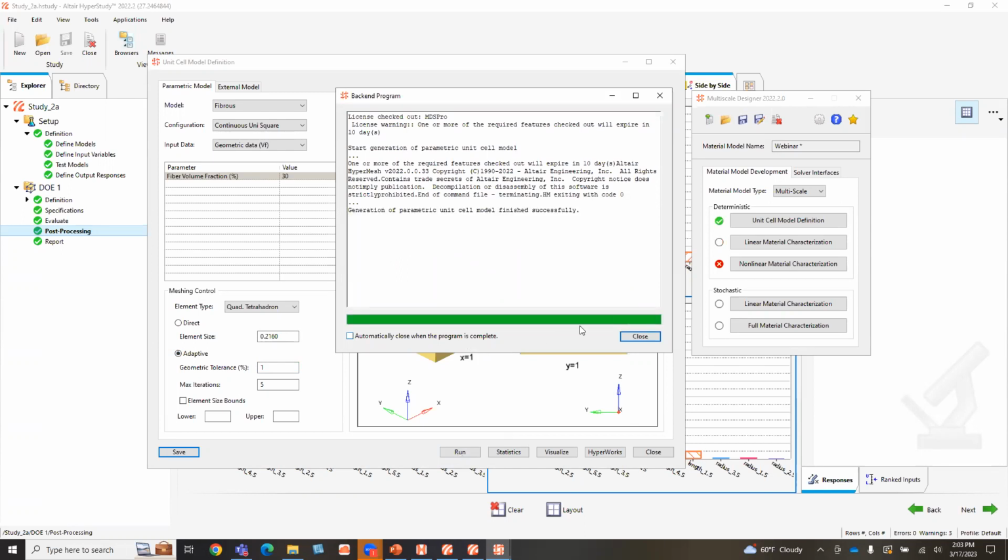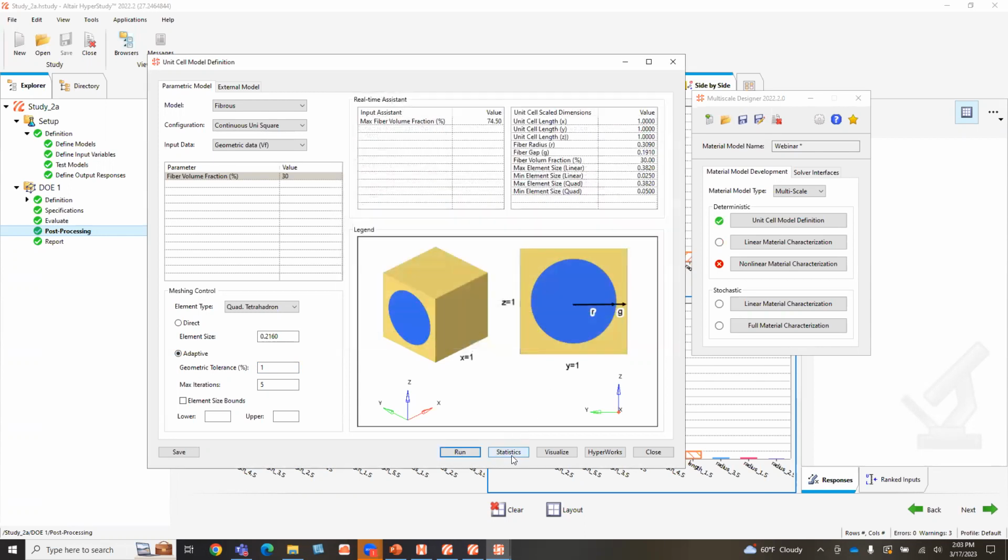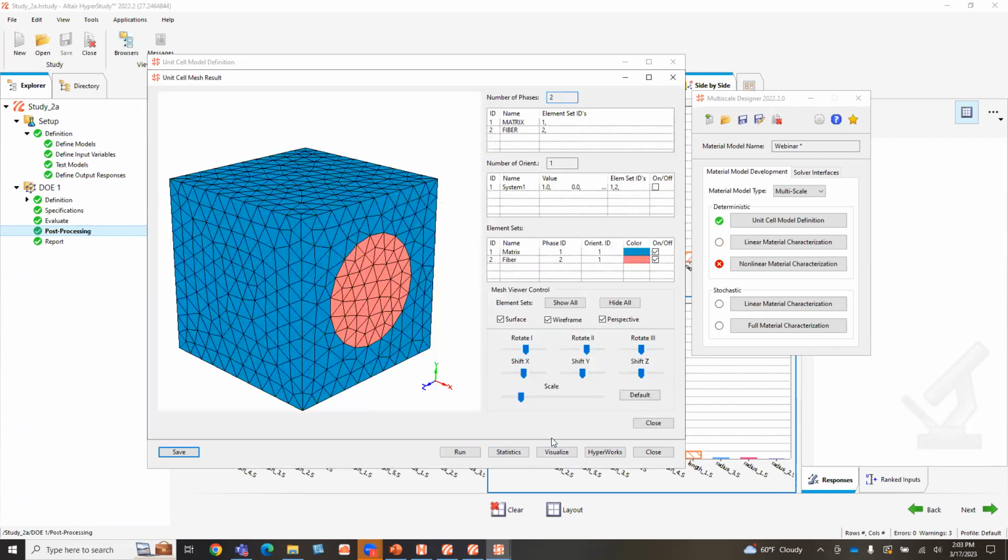it does this pretty quick. And so let's visualize what exactly I'm talking about. So if I go to visualize here, you'll see that it's creating the fiber and the matrix. And it's doing that through kind of creating these individual elements. And what we'll see next, because I'm actually going to apply the actual materials, it's going to give the materials and homogenize them to kind of make an accurate perspective of the material for each individual element here. So it's kind of doing all the work in the background for you of building the material card and giving a much more accurate representation, for, in this case, a carbon composite, but it could be for an injection molded model or what have you.